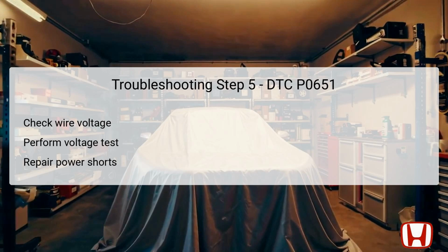If battery voltage is detected at the terminals, it signifies a short to power in the VCC wiring, necessitating repairs to restore proper connections. Conversely, if no voltage is present, it indicates that the VCC wires are functioning as expected. In such cases, it's essential to check for any authorized service information related to the symptoms you are troubleshooting, or consider substituting a known good TCM and re-evaluating the DTC status.